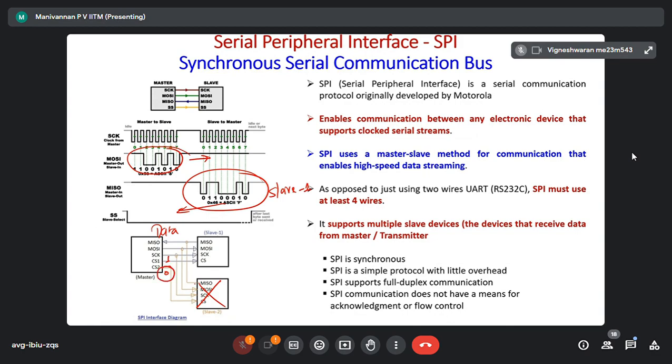CPU disabled. By making chip select equal 0, that means this fellow is permanently disconnected. Electrically connected, but it's not allowed. So the communication happened between these two. So there's no arbitration. Arbitration happens only if both these slaves are trying to reply. So the data is from slave 1. Correct? This can be given only by it because clearly you have selected slave 1.